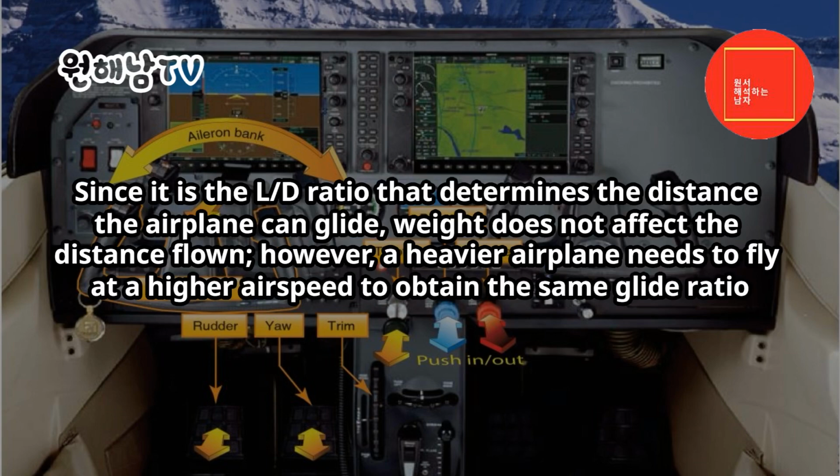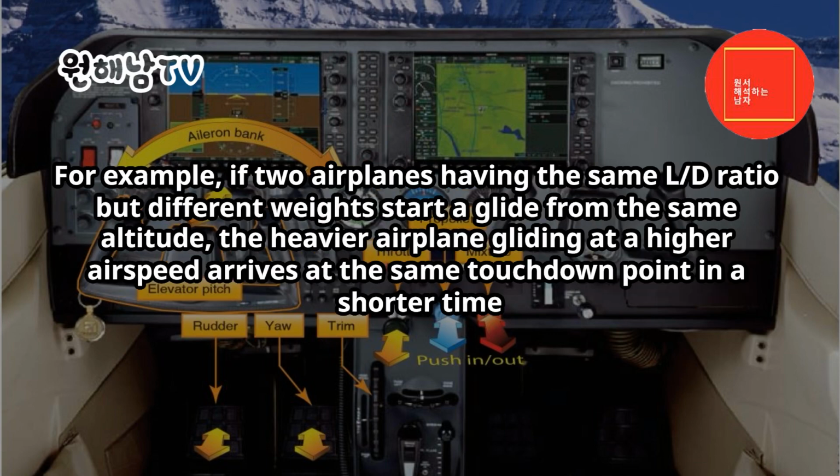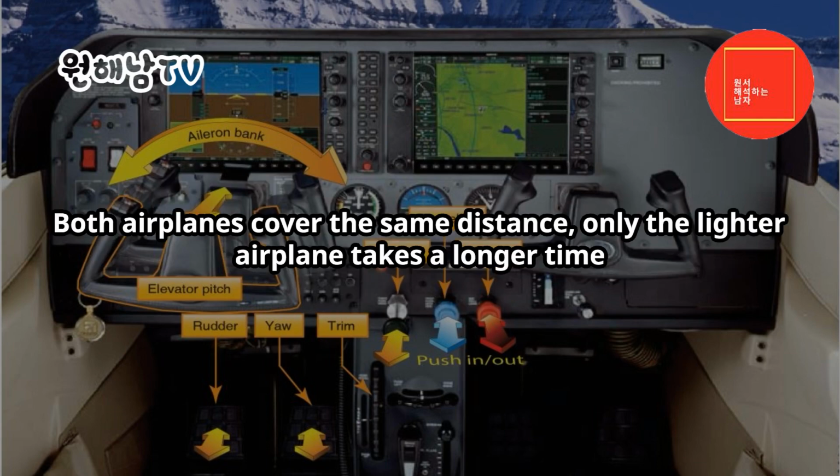Since it is the L/D ratio that determines the distance the airplane can glide, weight does not affect the distance flown. However, a heavier airplane needs to fly at a higher airspeed to obtain the same glide ratio. For example, if two airplanes having the same L/D ratio, but different weights start a glide from the same altitude, the heavier airplane, gliding at a higher airspeed, arrives at the same touchdown point in a shorter time. Both airplanes cover the same distance, only the lighter airplane takes a longer time.